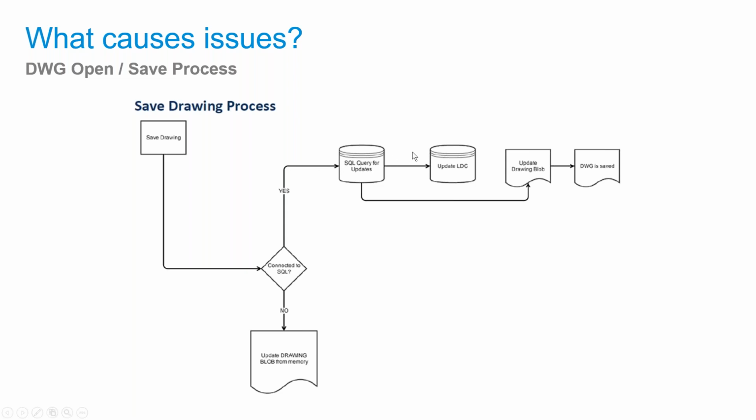Hey Jason, we have a question in the Q&A about how does that drawing open and save process change with cloud collaboration? And we should just talk about the local cache. Yeah, it's a little bit different there. And same thing would be for a Vault environment, where as you're working, you're checking out these drawings and you're really working on a local SQLite project. So if you save the drawing, it's writing to that local collaboration cache folder.